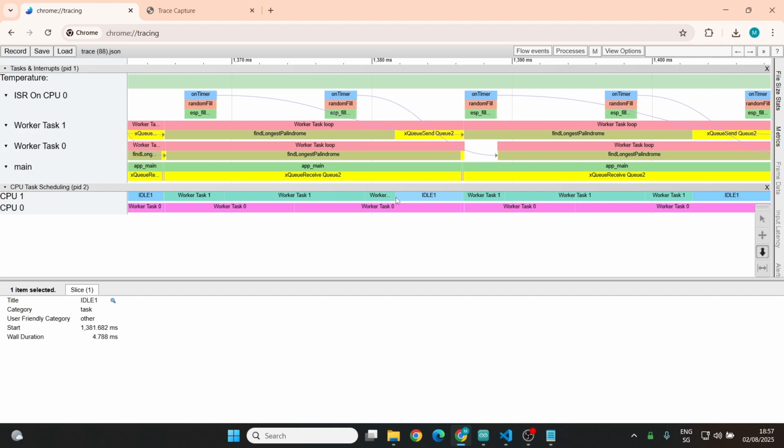So we would actually want to see, at least here, where the task gets blocked and a task switch can happen, we would hope for it to switch to the main task so that it can process items here. We actually would want it to process already sooner than that, but no later than this. The idle task has the lowest priority 0, and the main task by default has priority 1. So it's very weird that here we don't see the main task running.